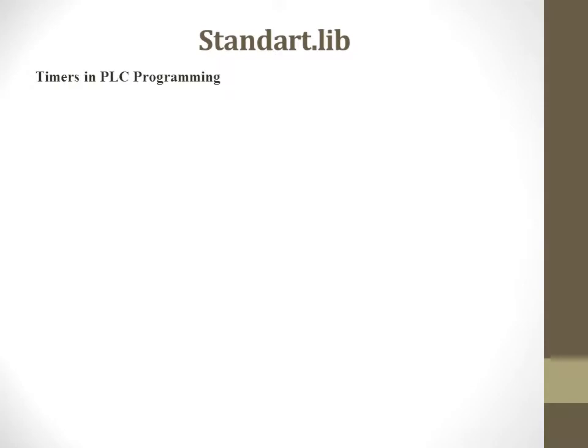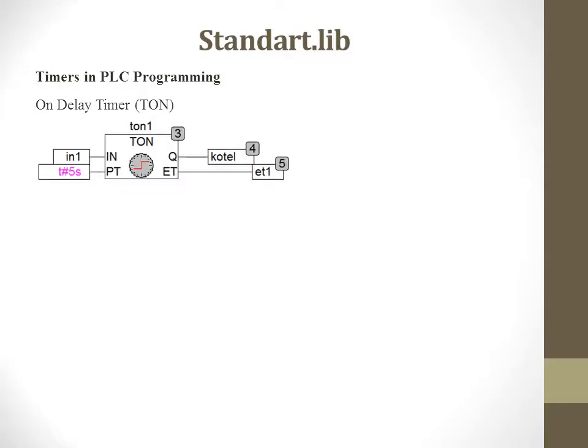So, the next set of function blocks is timers. The first timer we call the on-delay timer. The abbreviation is TON. This is the picture of the TON timer.